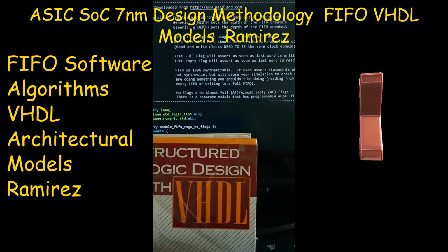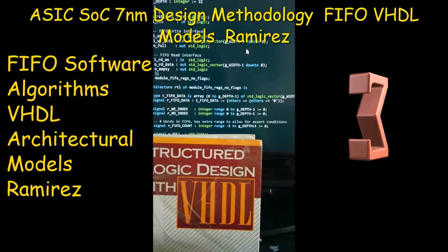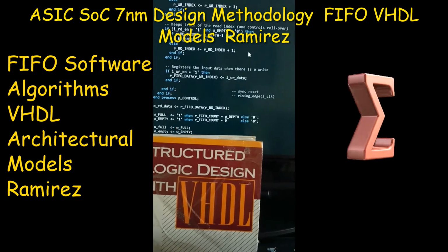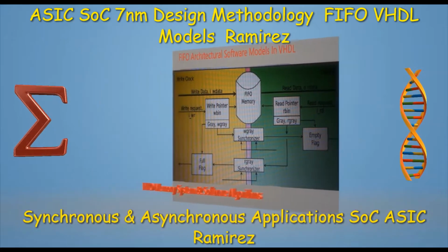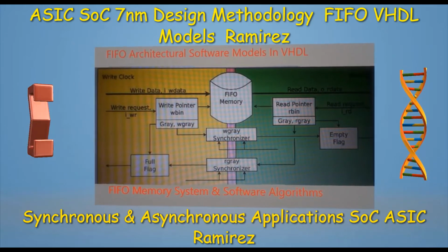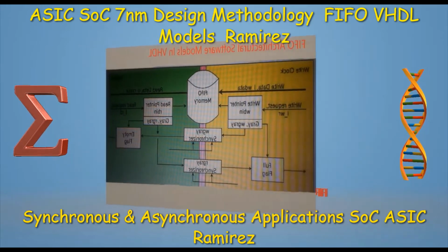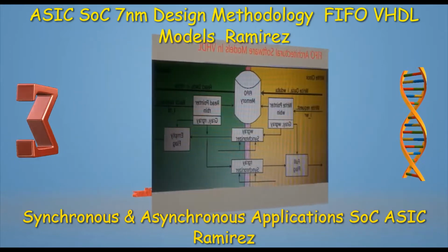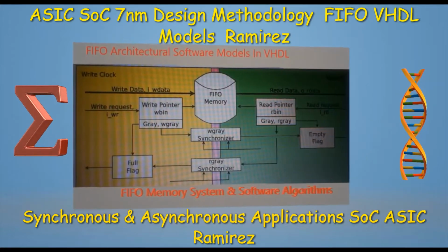As a result, the FIFO needs to buffer the data that need to be stored during the write cycle until it has been read in the read clock domain. So the depth of the FIFO depends on the data to be stored.